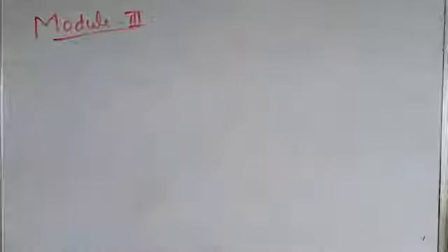Today we are going to start the third module of our course on flexible AC transmission systems. So we are going to start module 3. In module 3 we will be mainly discussing various shunt and series compensators. Shunt compensators especially are SVC and STATCOM, and then there are different types of series compensators also. So in module 3 we will start our discussions on the first type of shunt compensator, that is static VAR compensator,